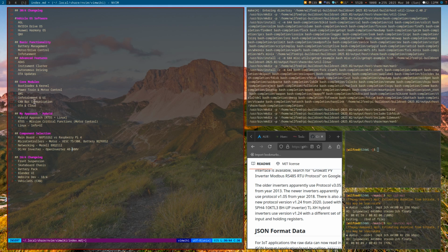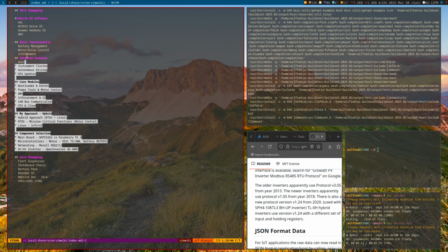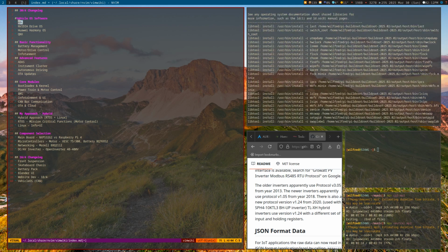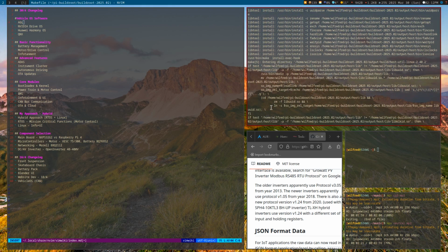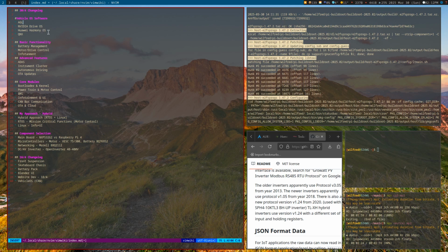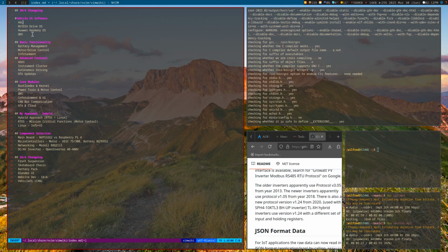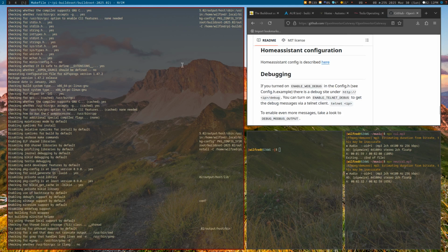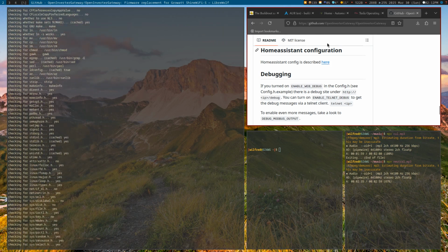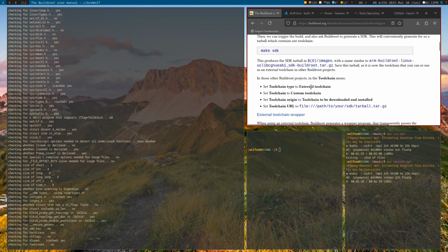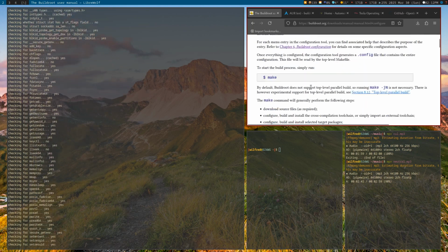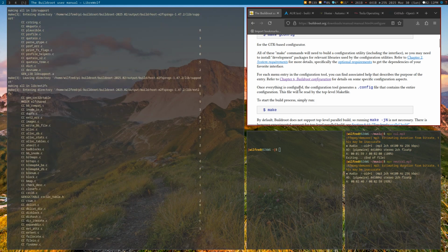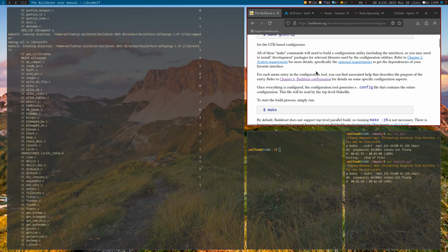There's a lot of interest when it comes to automotive grade Linux. Because I've worked with it before, I know its ins and outs. But my approach to this would be to build something from scratch, and that's the reason why I chose to use Buildroot, because it gives the ability to choose exactly what components you require, rather than having a desktop OS running on a very important piece of software like a vehicle controller.